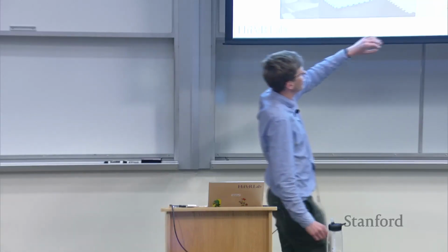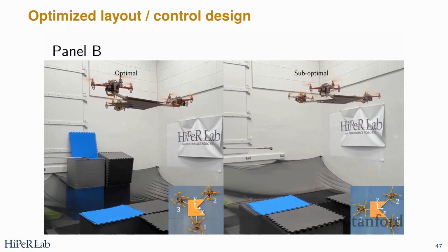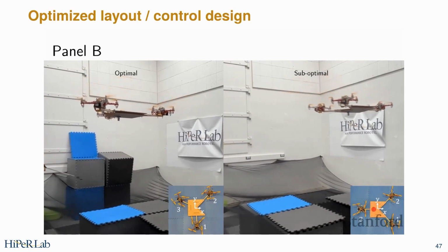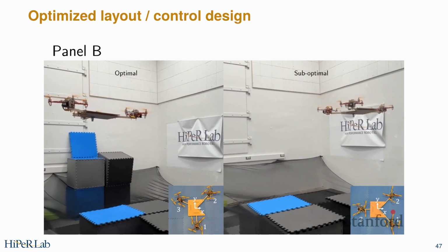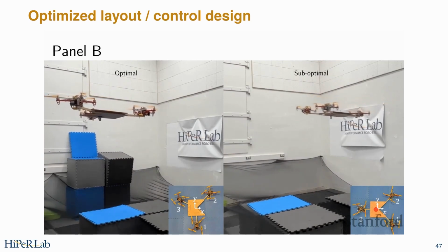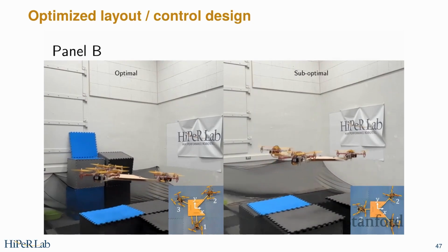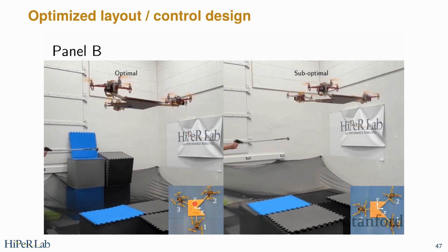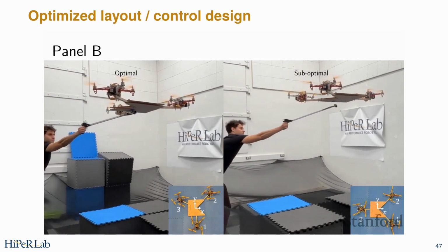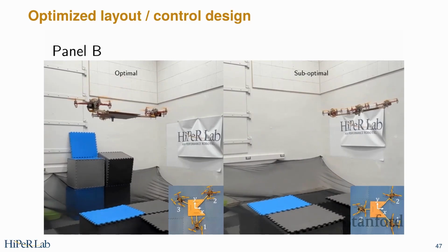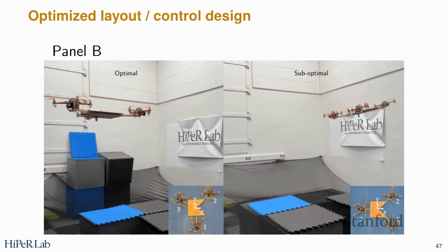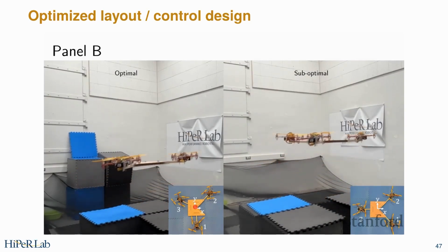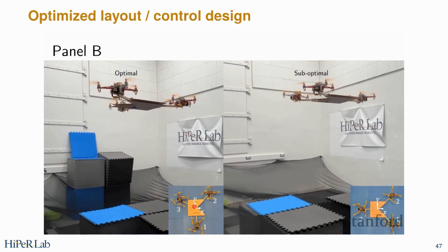So I think it has to do with where the center of mass is and how the inertias are. So here, the center of mass is somewhere over here, right? Because you're removing this piece. So somehow, these 2 agents are much farther from the center of mass than the third one, right? So I think in this configuration, in the open loop sense, the open loop forces will be smaller. It's a combination of the open loop and the closed loop. And I think both of those will be more favorable, both the controllability aspect as well as the open loop forces, in this configuration than in the right-hand configuration.